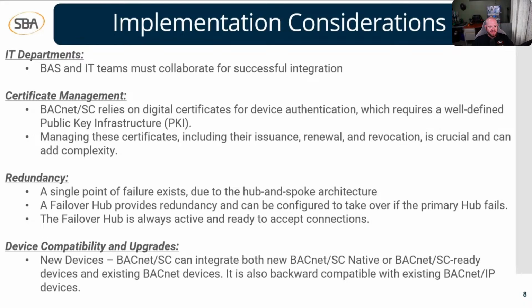The next thing is certificate management. BACnet Secure Connect relies on digital certificates for device authentication, which requires a well-defined public key infrastructure, or PKI.